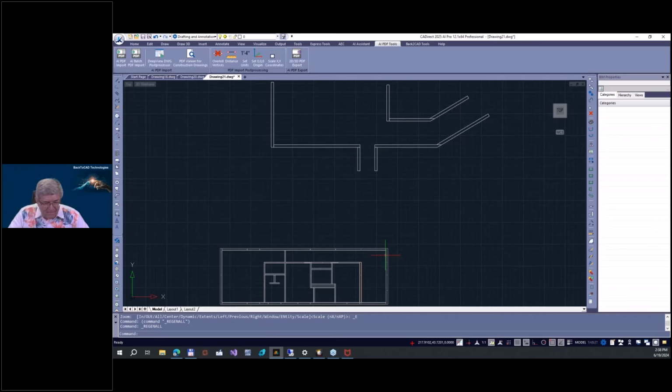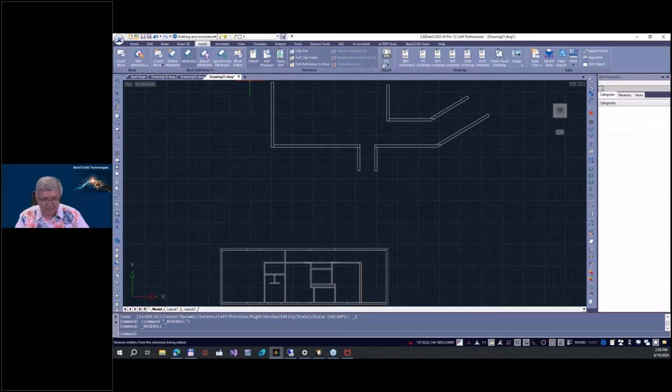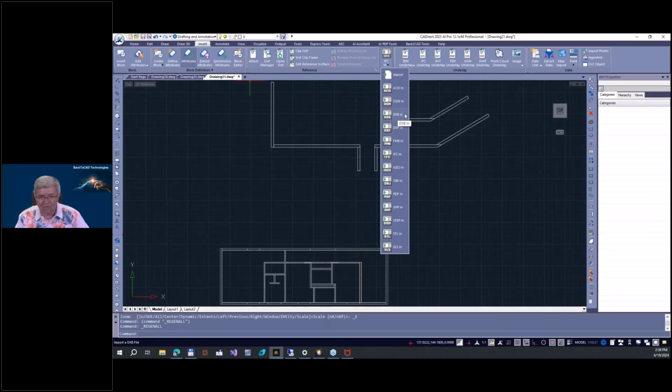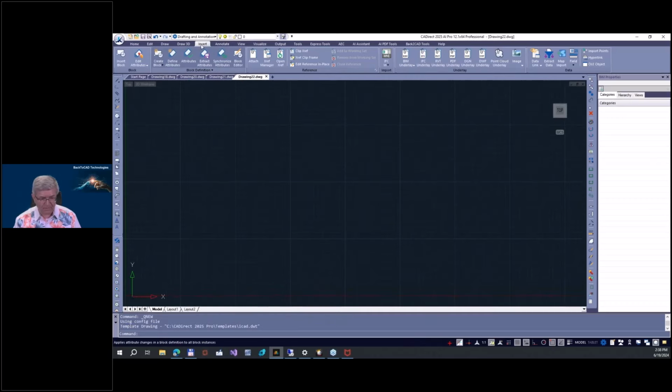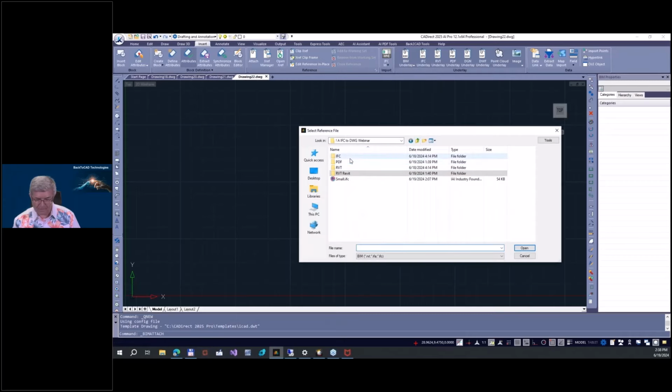Okay, very important thing is that you can use again insert IFC import if the file is small and you know the structure. If you have big files, you have to separate what you want and then you can import it. But there's one warning. I show you something. Let me insert now another one, beam underlay. This time I take again IFC with this small house.